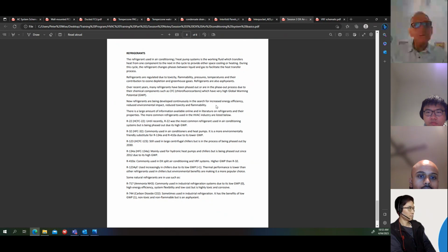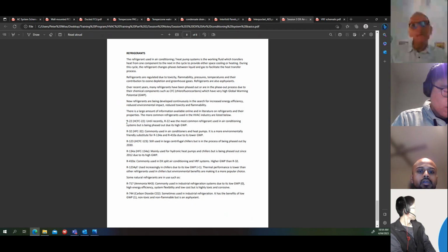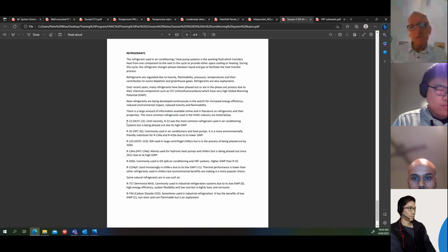Generally, the ones that you'll come across: R22, that's being phased out. That used to be the standard refrigerant for DX split systems. But it's still available, and there are still some units running on R22, but they won't be replaced with R22.